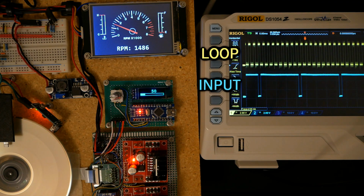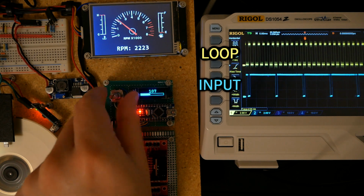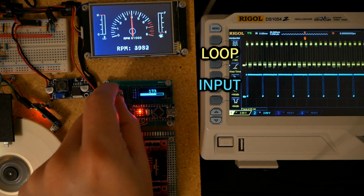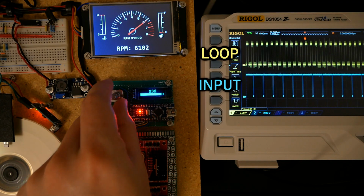This is important in cases where it's critical to not wait for the loop to execute something. As we know, the loop executes the codes over and over, usually very fast, but sometimes we want to register changes in the input that can happen too quickly, much faster than the loop. These are the cases where we use an interrupt.